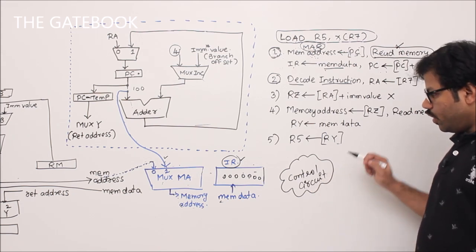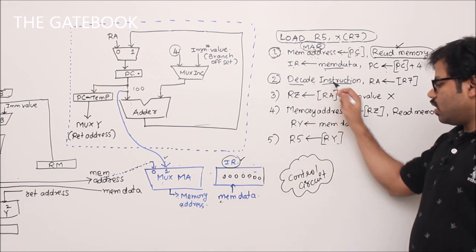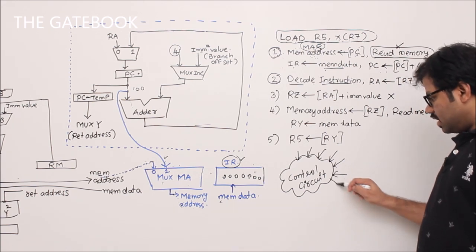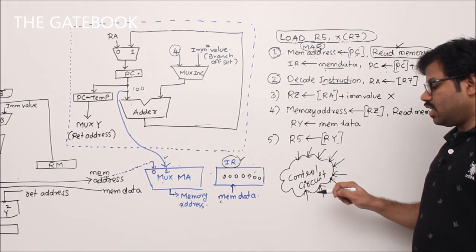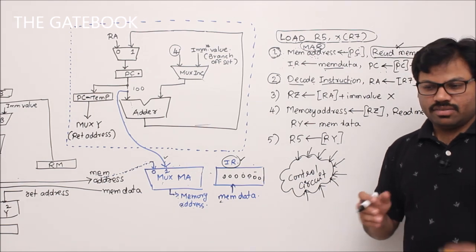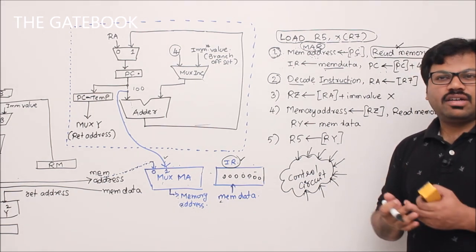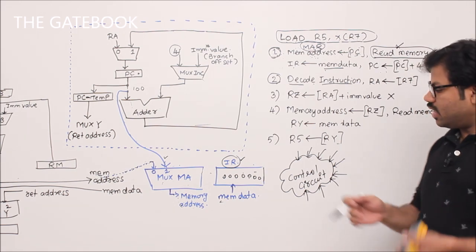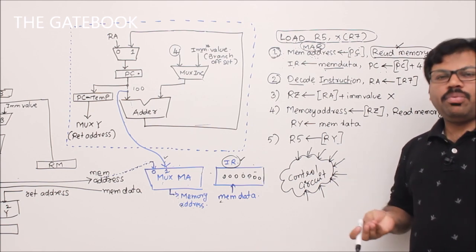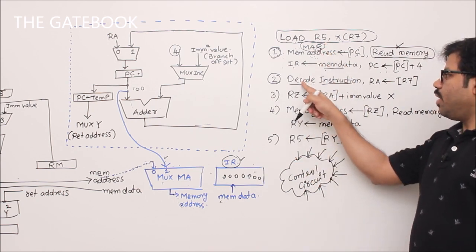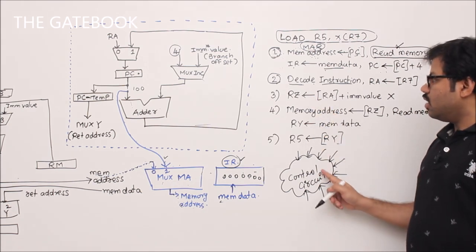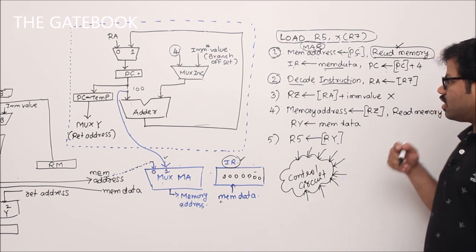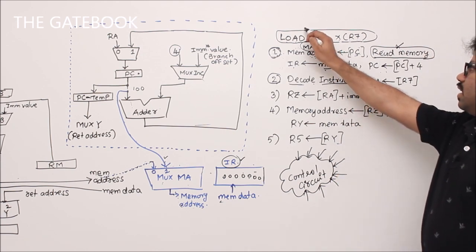That control circuit is going to decode the instruction, and it is going to understand the meaning of that instruction. Is it add, subtraction, multiplication, and apart from that, is the instruction immediate mode addressing, direct addressing mode, or indirect addressing mode. Everything will be understood by your control circuit, and appropriately it is going to take the operations. So the remaining operations will depend on the decoded instruction. Let's say that instruction is properly decoded and your processor understands the meaning, then it realizes that it is a load instruction.